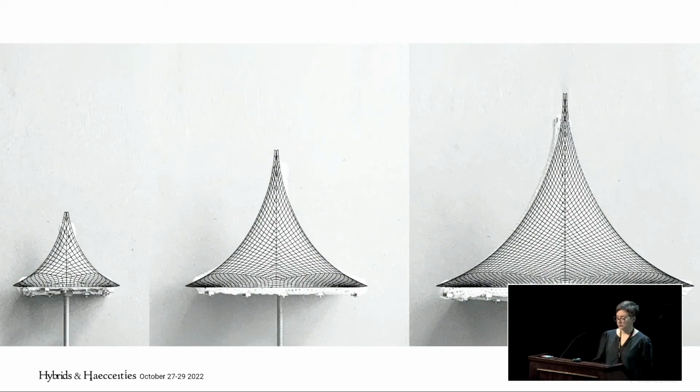Also, the simulations in this study are done for a series of models of the same shape, but at different scales to understand the behavior change across the scales. As we scale up, the number of stitches in the actual physical model increases, as does the number of mesh faces in the digital model. This increases the computational process time, and one solution would be to pack a series of the mesh faces into one mesh face. How reliable the model would be is the topic of another ongoing research.